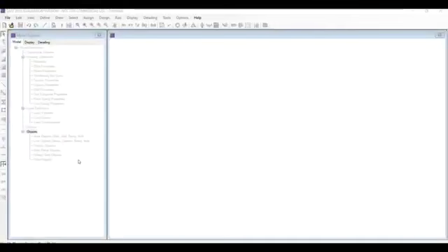Hi guys, now we are going to design a footing called the mat footing. For a mat foundation design, firstly we need to have the resultant values from our previously designed building from any software like ETABS, SAP, STAAD Pro, or anything. We need to have the axial forces of the columns at the base level or the shear forces of the columns at the base level.